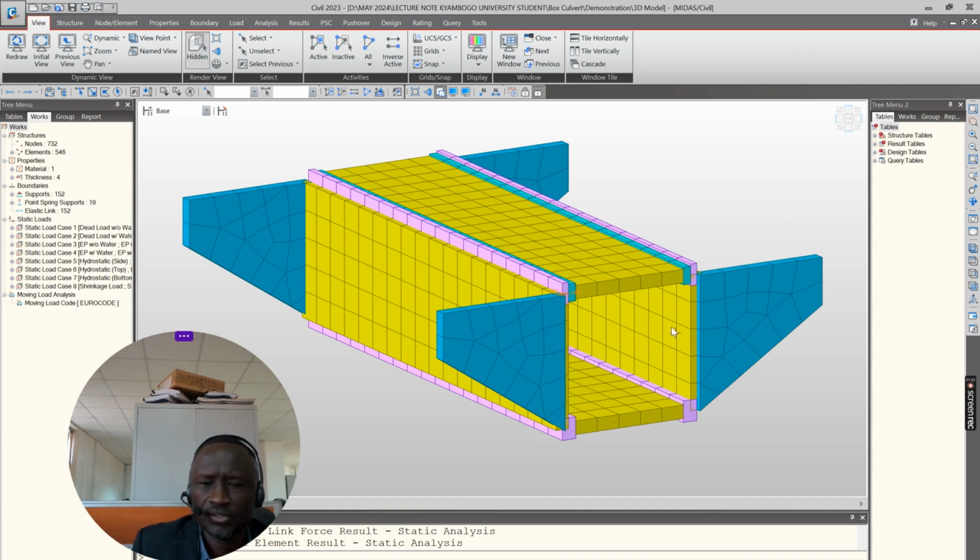Here I'm going to remove this wing wall and then develop one model, the flaring type with the apron. This one has no apron, and this will be very expensive in terms of special maintenance, because water at the outlet and inlet will be piping. So you have to do an extra treatment at the inlet and the outlet.